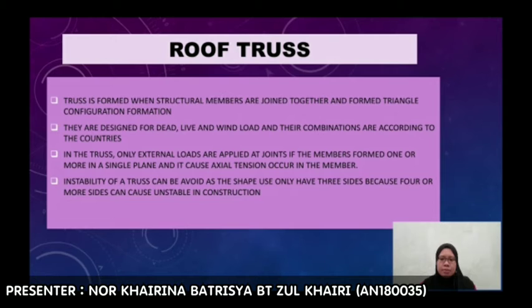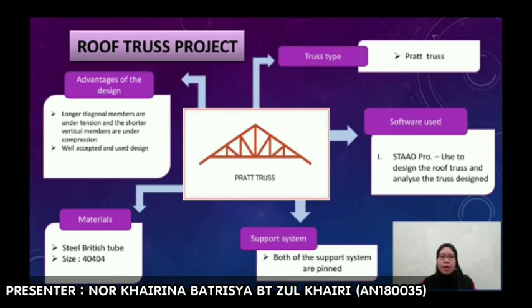Instability of a truss can be avoided as the shape used only has 3 sides, because 4 or more sides can cause instability in construction. Then we continue with the roof truss project. In our project, the design for truss uses Pratt truss. For software, we use StaadPro to design the roof truss and analyze the truss design.